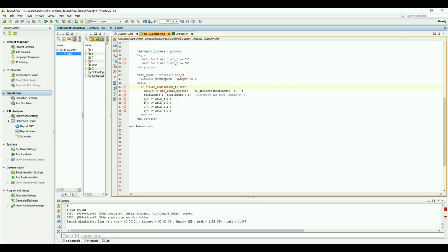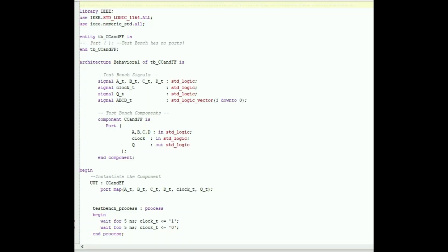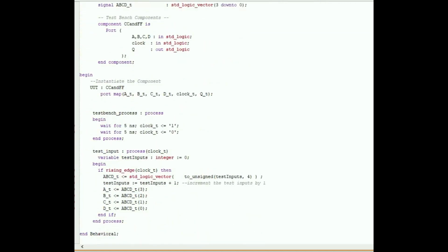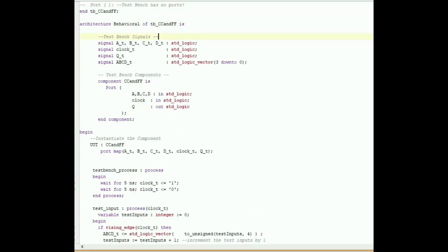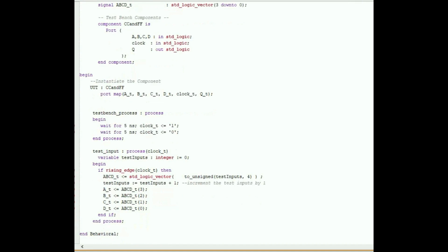This is just a simple VHDL tutorial. But anyway, that gives you a fairly decent idea. I'd recommend functional testing for your modules, not exhaustive testing at this stage. You just want to make sure it works as expected. Does it reset? Does it initialize? Are the outputs what you would expect? And so on and so forth.